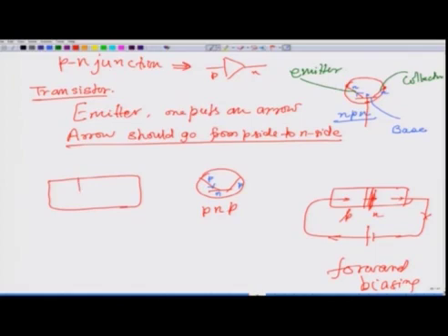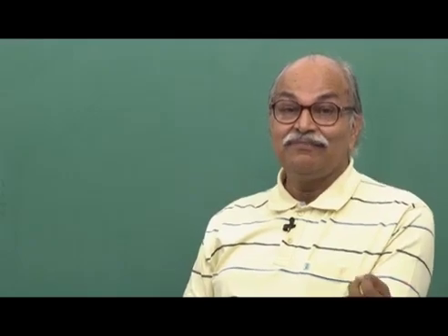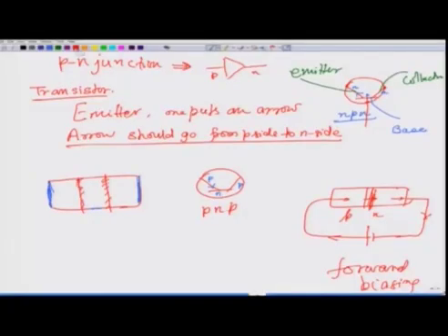silicon base where you have these two junctions and then you have the depletion layers and all those things, and if this is your NPN or PNP transistor, you must have some metallic contacts. So, you should show the contact somewhere this end, somewhere this end and somewhere on the base. So, you have 3 metal contacts to connect to the outer circuits: base, emitter and collector, all 3 need metallic contacts. So, those things are represented in the symbol by say this point here and then the 3 points which are here. So, I draw a line here also, and this point the metallic contact, this point the metallic contact, this point the metallic contact. So, these are the symbols for transistors.